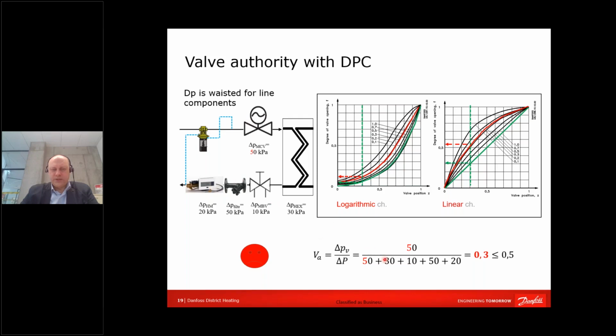So we have to add all these meters, exchangers, balancing valves, and we are ruining control characteristics. That is a wrong way to do so. But somebody is doing it. So consider this scenario as a wrong one.